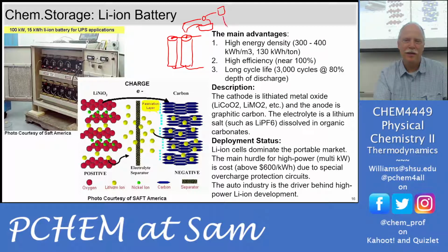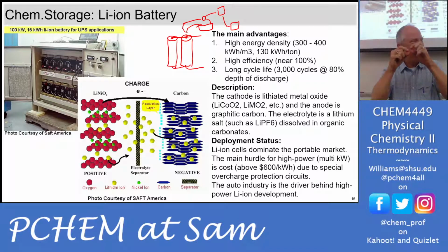And then he has a foot pedal. You put the copper wires right on that nickel strip and step on the foot pedal, and it goes pow. That current running through that nickel strip is enough to weld it to the top of the battery, and yet you don't heat up the battery and cause it to break down.